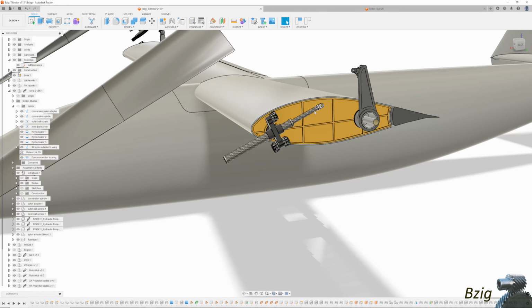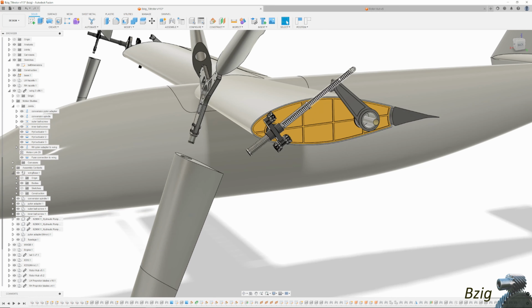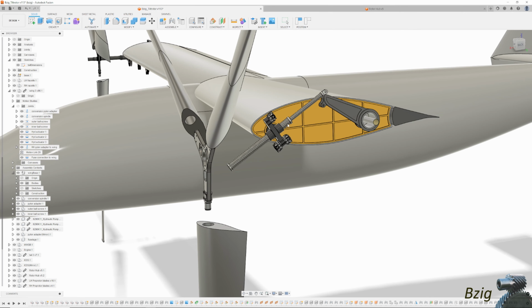I actually tried to make my design simpler by using a single-stage ball screw, but I found that it wasn't geometrically possible. A single screw was just too long. When the nacelles were positioned for wing-borne flight, the screw was impractically too far ahead of the leading edge of the wing. It would have interfered with the prop rotors.